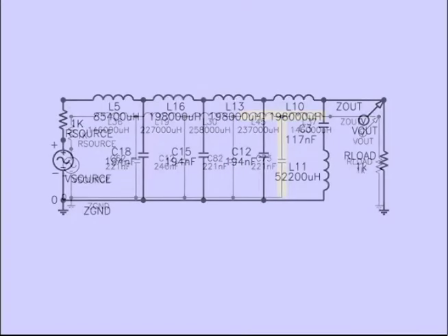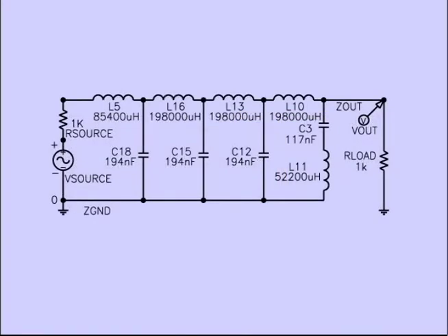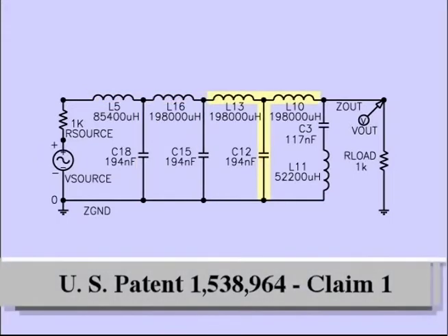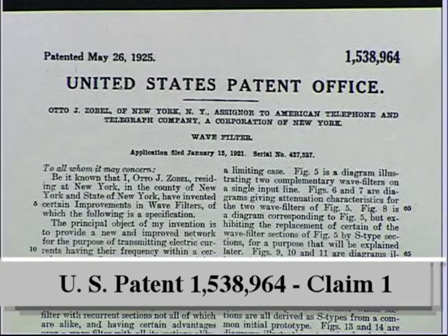The 100% compliant solution evolved on yet another run infringes on the patent of Otto Zobel, which combines several T sections with a special half section to produce a sharper frequency domain transition while using fewer components.